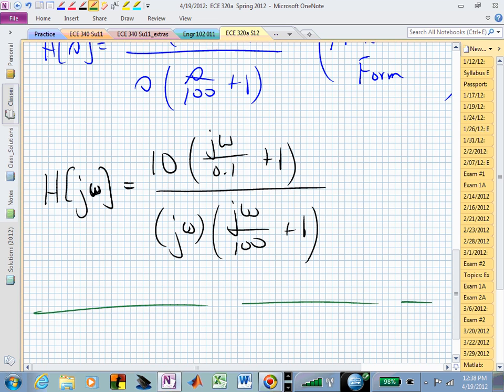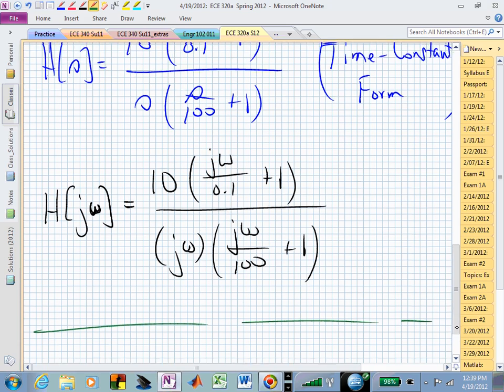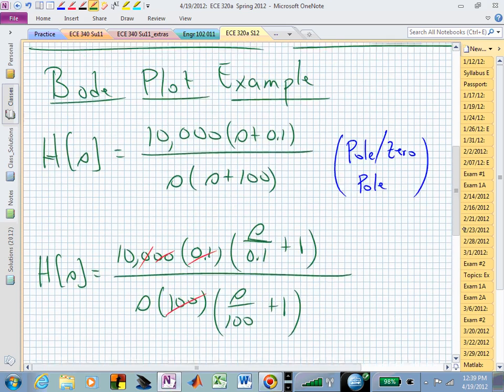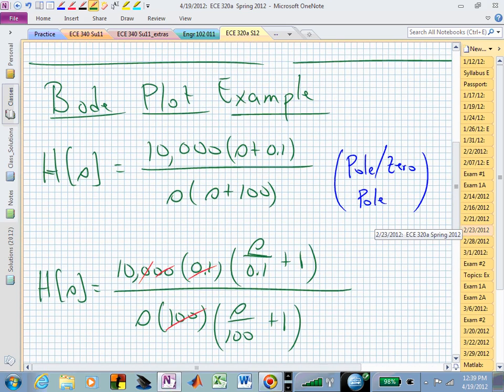And now you could still do the initial value theorem on this transfer function. I like to go back to this form if you were doing the initial value theorem. As long as the limit exists, and it will in this case, you multiply H by s. And can you apply the final value theorem on this?